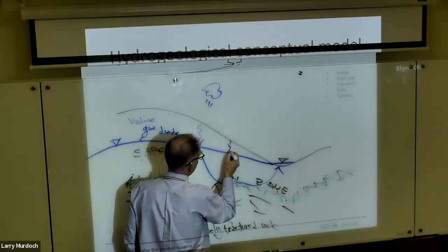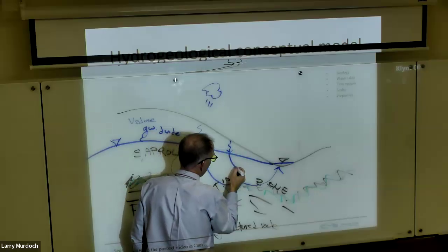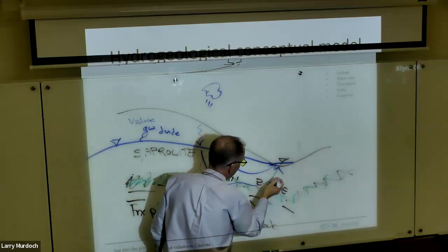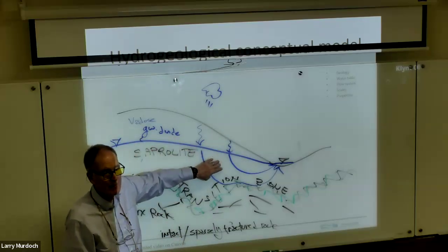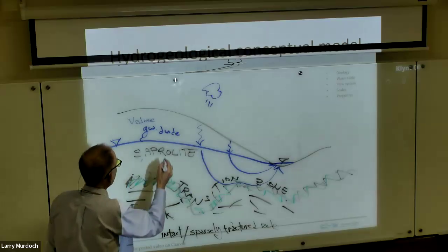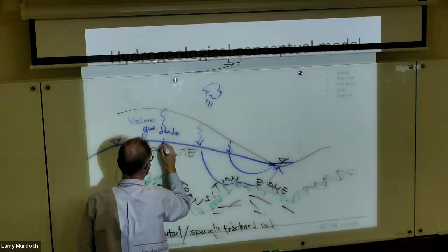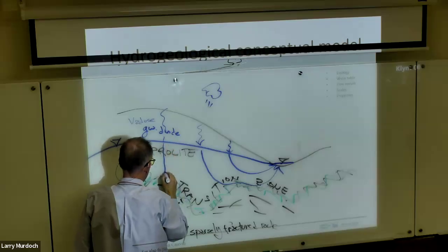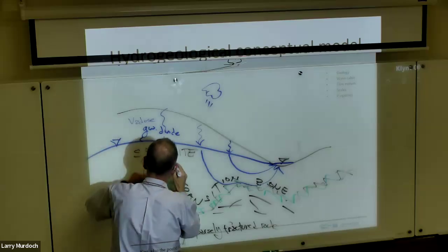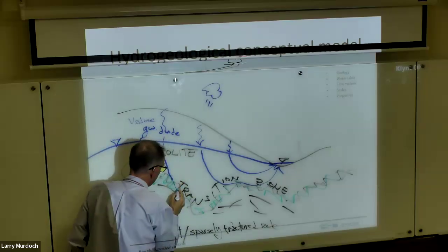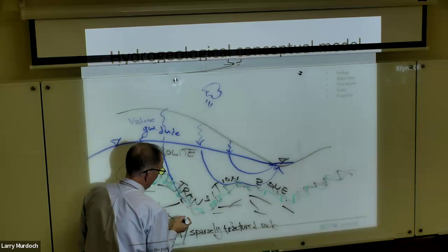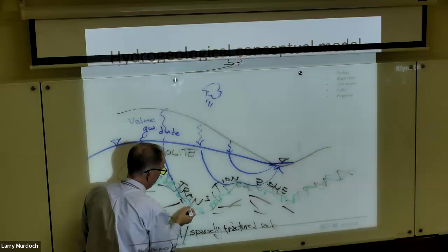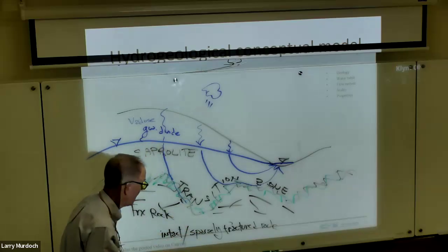A flow path like this is going to go in, and remember, these flow paths can't cross. So there's a flow path that just stays in the saprolite. And then another path that goes here and comes down and gets in the transition zone. Transition zone, we think, is a little bit higher permeability than the rock around it, so it'll be preferential, but it's not all that high.